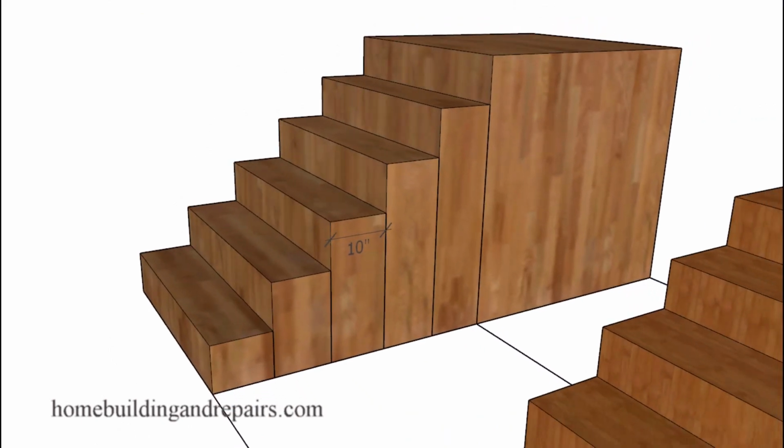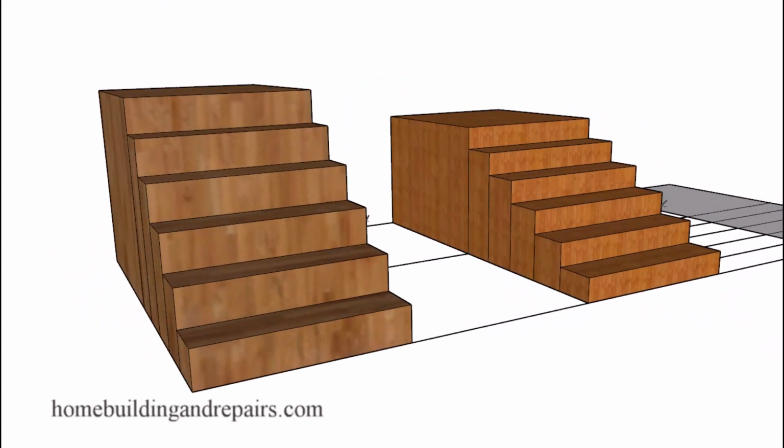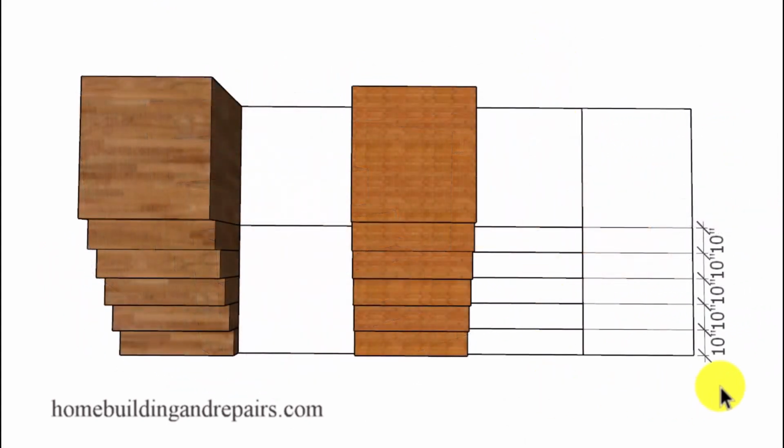And like I said, you're going to be better off if you don't know a lot about stair building. And that will be to lay out the basic design of the stairway on the ground or on your building foundation floor or even on a sheet of plywood, something that will provide you with a design of the stairway that can be used to pull measurements from if needed to build your stairway. So again, check with your local building department to find out the minimum and maximum sizes for your treads and risers, along with the minimum width of the stairway before building your stairway.